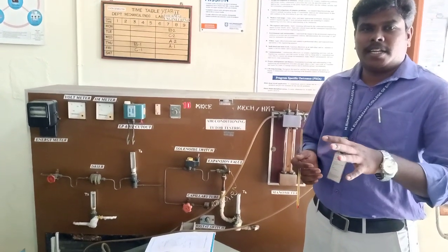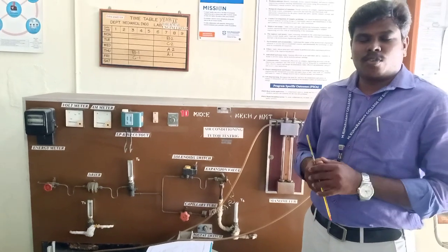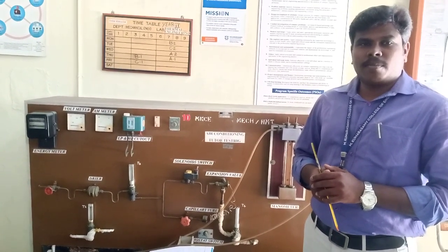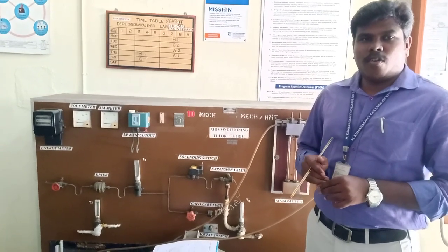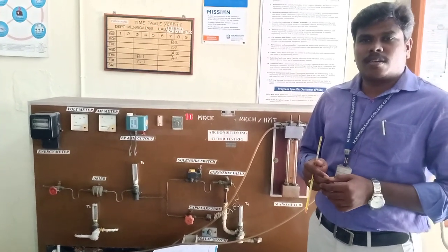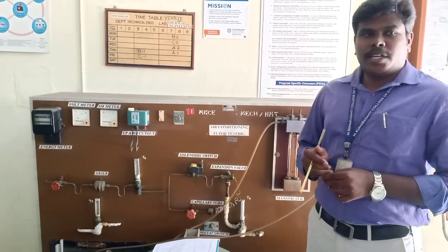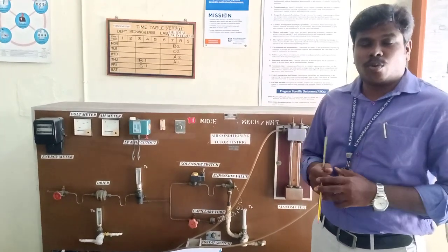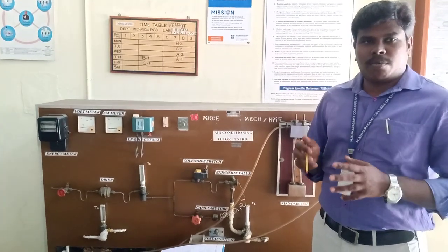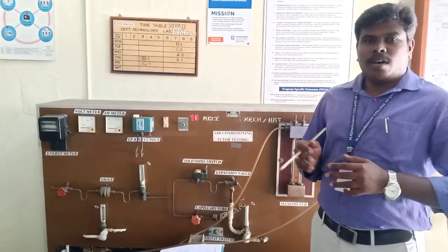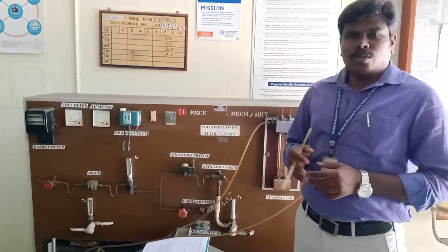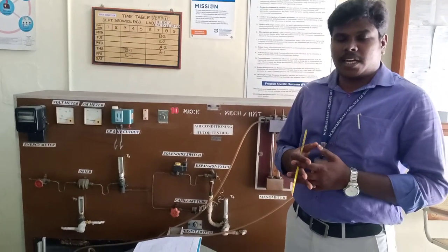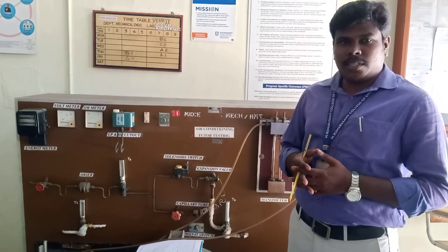Refrigeration does not maintain the atmospheric psychrometric levels, such as humidity of air, dry bulb temperature, and wet bulb temperature. Whereas in air conditioning we need to maintain human comfort, so we need to maintain the CO2 level inside the air conditioned room. Also we need to maintain dry bulb temperature and wet bulb temperature for human comfort. Okay, so air conditioning follows the basic law, the second law of thermodynamics, Clausius' statement.